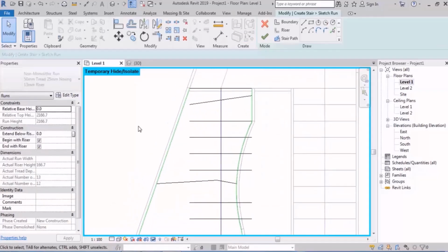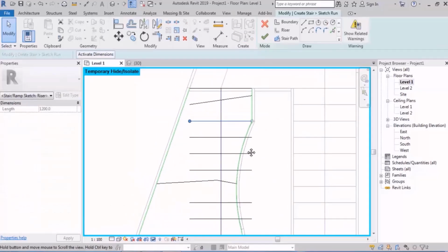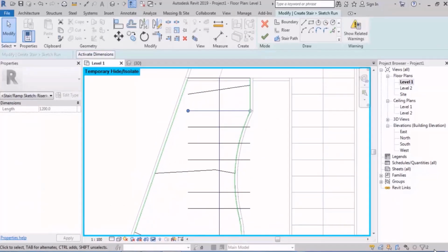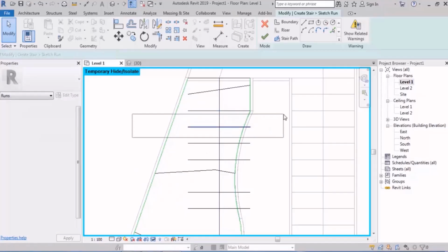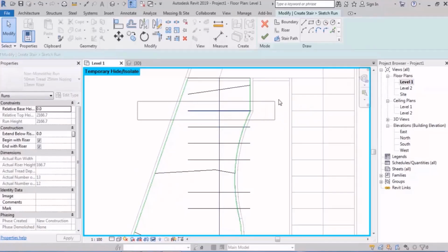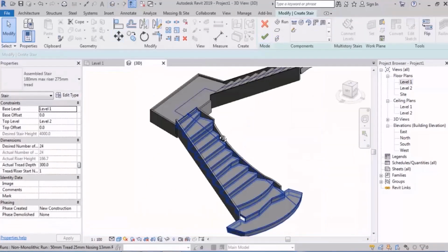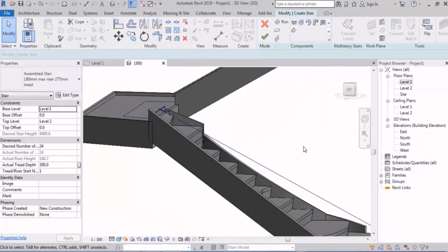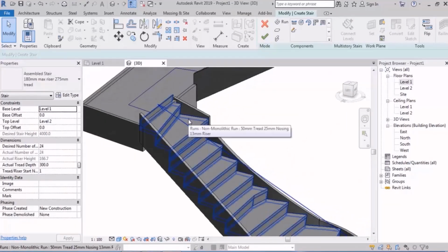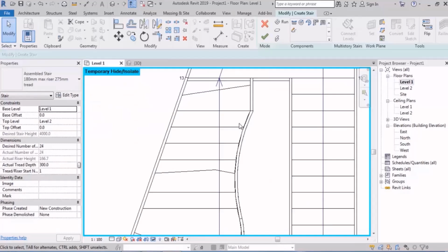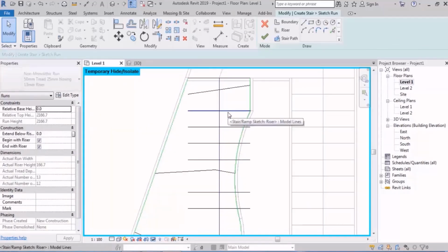Well, it's a bit difficult to find this, but when you open a box, if you see down there, it shows 2. This one, it shows 1. This one, 2. It's a common error that appears when you have 2 risers on each other. You can also see it in 3D. You see, just like this. So, be careful. It's so common, it happens a lot, that you have 2 risers on each other. Remember that.